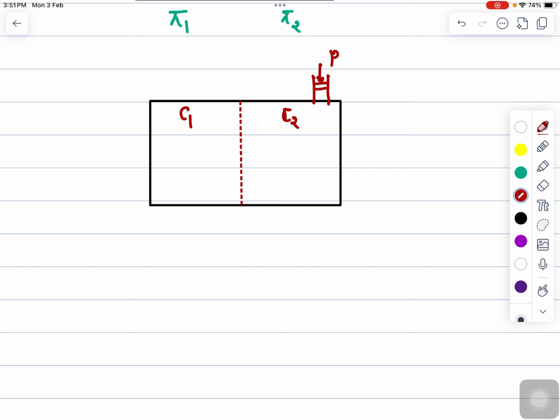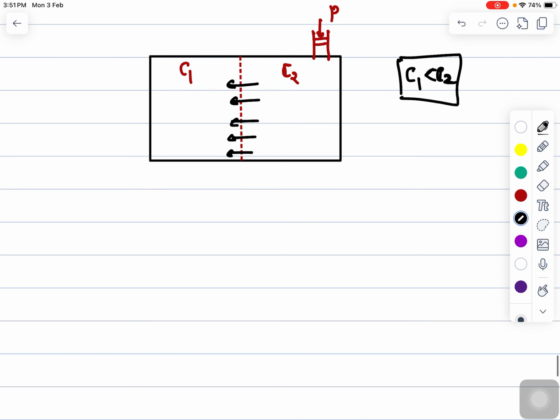So pressure is being applied. So due to this, again concentration C1 is less than C2, but here the solvent will start moving from higher concentration side to the lower concentration side. Is that clear? And you can see that if pressure difference delta P is greater than delta pi here, then the reverse osmosis will start taking place.